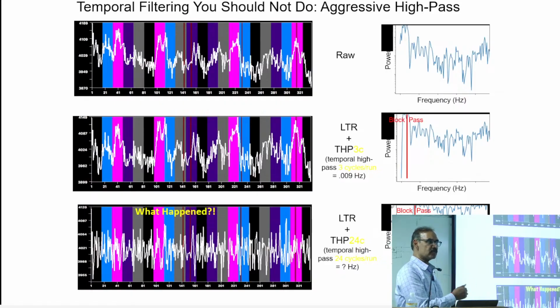That is information we can use. We cannot see the heart rate, but the respiration rate we can see. If we know that for kids it is 0.3, while for adults it's 0.2, then we can use a band reject filter to get rid of those frequencies.